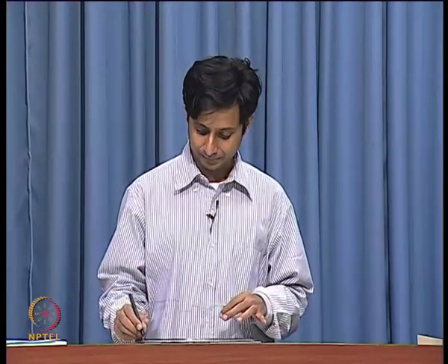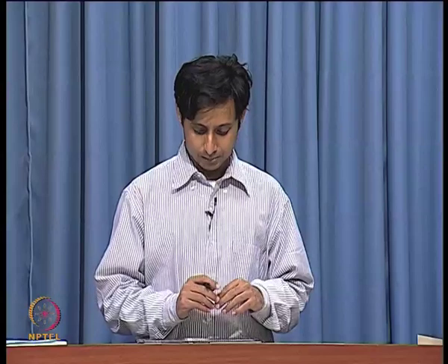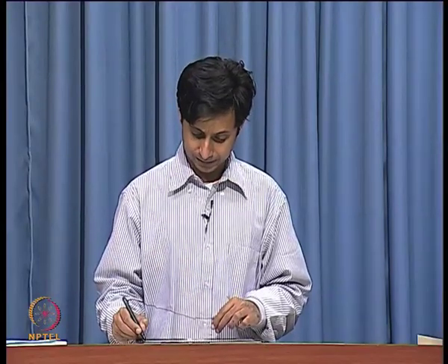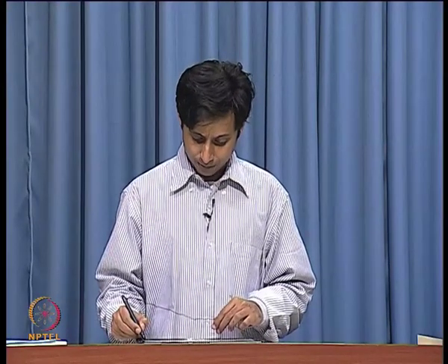The input of the mixer is looking like a capacitor. So, there is not going to be any power transfer at all. So, I can't do matching at all. So, that is problem number 1. Problem number 2 is maybe the capacitance is going to be too much, because you have to drive 2 sets of transistors. So, that is why we wanted to bring the RF to the bottom layer of transistors, the LO to the top layer of transistors, and this also works fine.